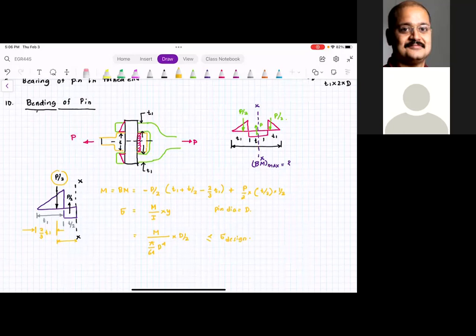There's the top part of the joint and there's the side part of it. Side, how do you know? The whole side part connecting them. Those dimensions are non-engineering dimensions, which means they are not the load-bearing dimensions, but they are important when you are actually trying to manufacture the knuckle joint. So those dimensions come from proportions. Now, how do these proportions come into the picture?